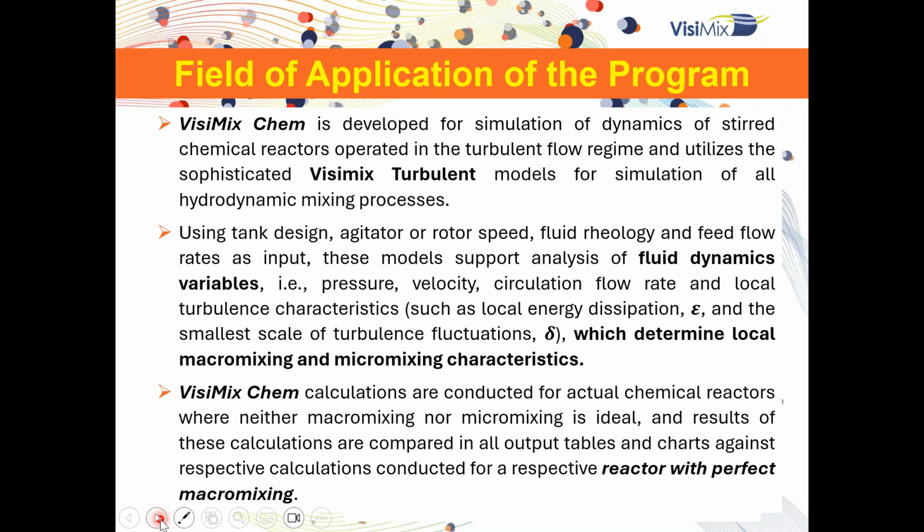We focus on the energy of dissipation, defined in the size calculated by Kolmogorov, or the connection to the Kolmogorov eddy size, and it gives us the capability to determine the macro mixing and the micro mixing characteristics. So we are talking about two levels. The first level is how the material is moving in the tank and how, once at every place, these materials are connected between them.